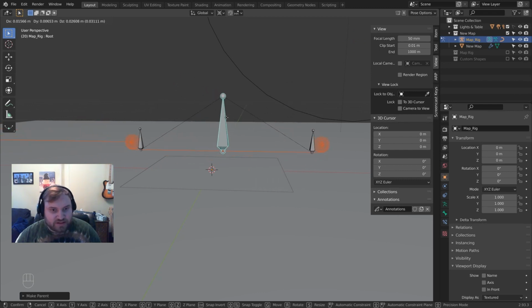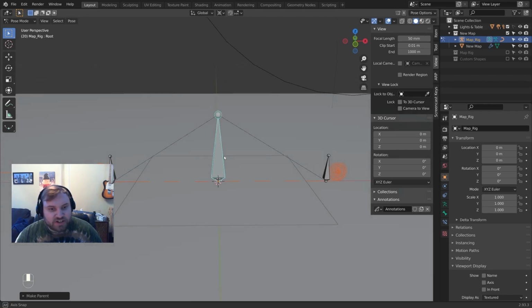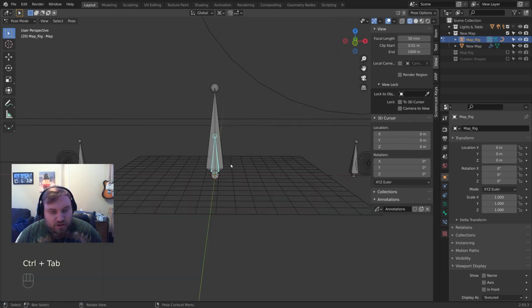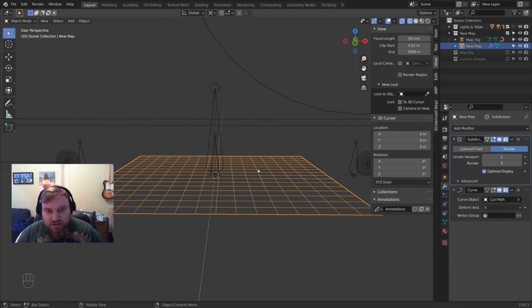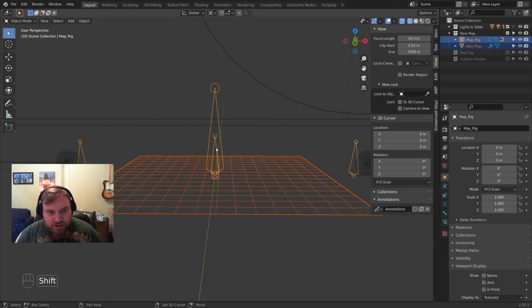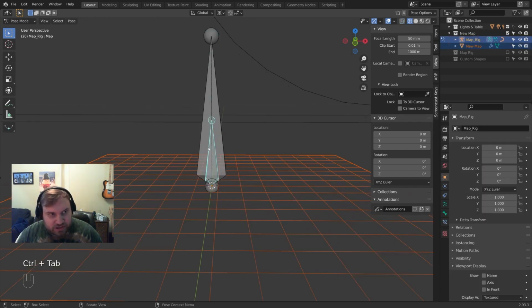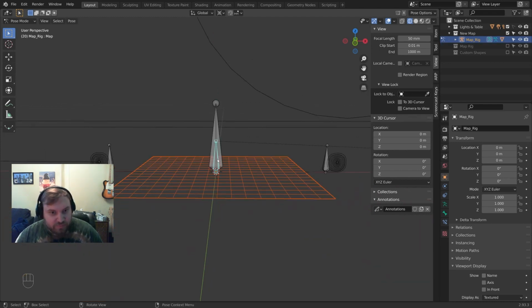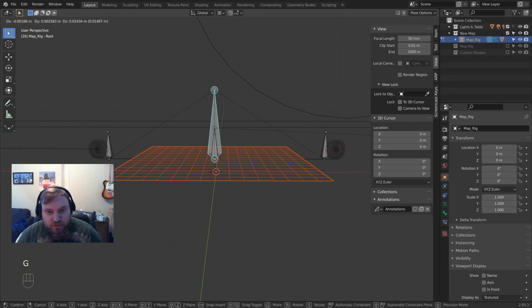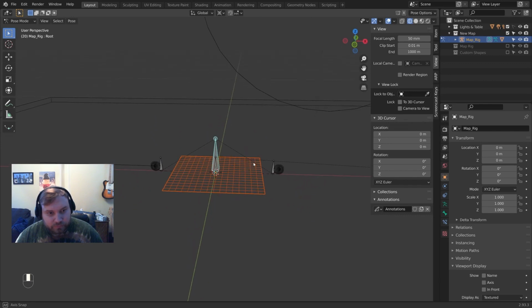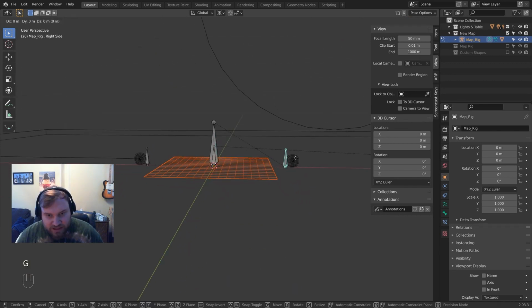The path is moving. What else needs to be attached to this bone? Because when I move the root bone, the map bone moves as well, it's going to be just fine if we just go ahead and click on our map, Shift click onto our armature, tab into pose mode here, and make sure we just select our map, and we can do Control P and parent to the bone. And again, because the map bone is already parented to the root bone, if we move the root, everything moves just fine. The next steps are just getting this thing working right.